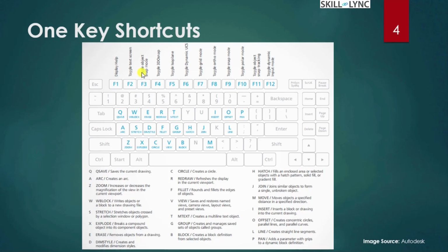If you don't use these shortcuts and you have to toggle them, then you have to invoke the command separately. For example, for the object snap, you need to invoke the osnap command and then select the checkbox wherein you have to select whether snap should be on or off. Alternatively, in the command bar at the bottom, you have a toggling state, but this is the quick and straightforward method to quickly turn the different required modes on and off.